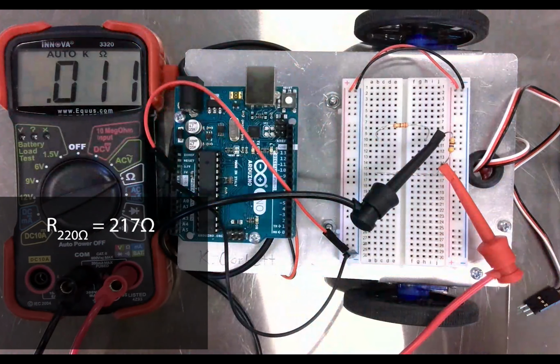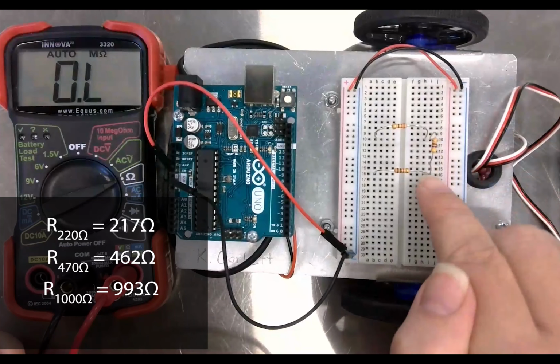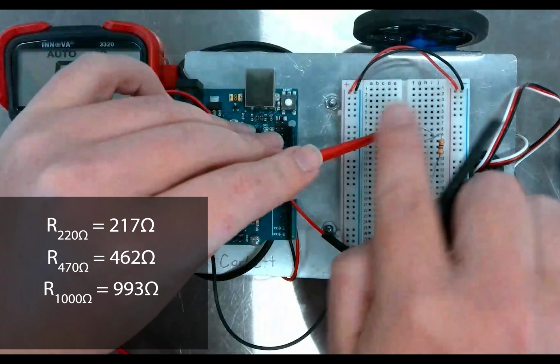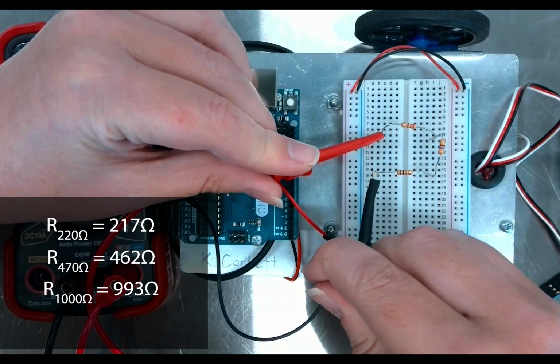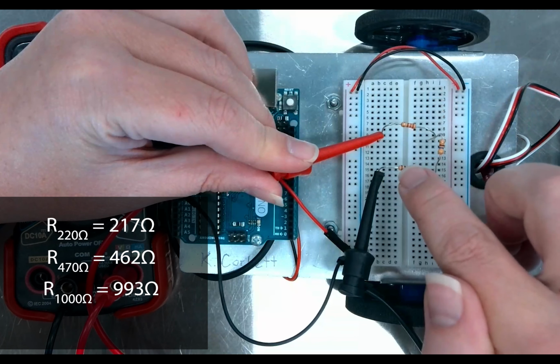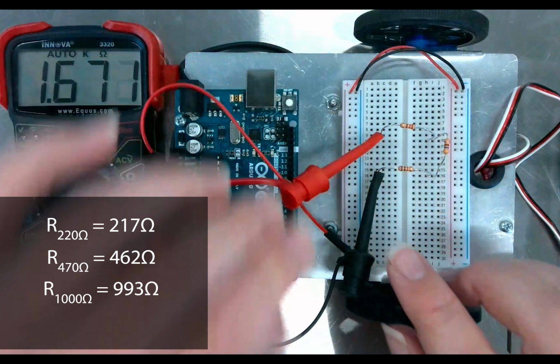Now, notice how these resistors are all connected. From this point right here, this resistor is basically like a loop. So we have this resistor that's connected to this resistor, connected to this resistor. So I'm going to take my multimeter and I'm going to measure starting at this part of this resistor. So starting at the beginning of the series resistor circuit, and then I'm going to measure at the end of the series resistor circuit. And so what that's doing is it's combining this resistor and this resistor together, and it's giving me the equivalent resistance that these three resistors provide.